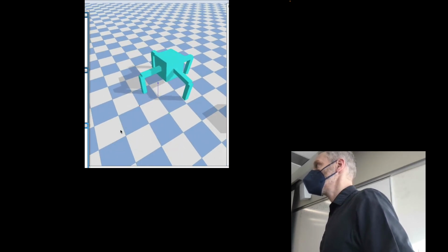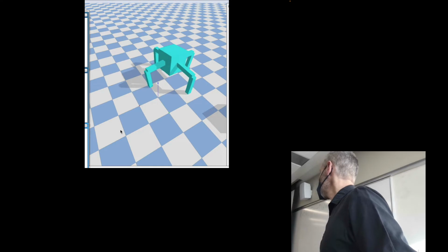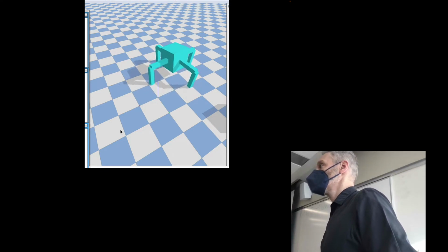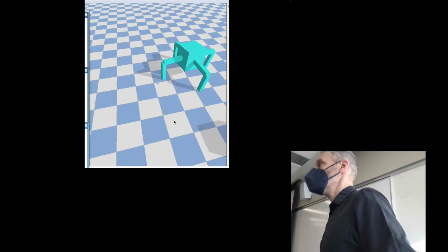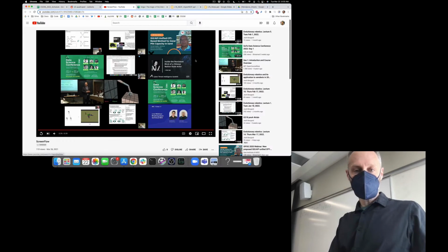We've got 8 joints, so you'll have 8 motor neurons, 8 motors. You're going to connect each of the 4 sensor neurons to each of the 8 motor neurons, which will give us 4 times 8, 32 synapses. If you want to add in hidden neurons, that's perfectly fine. Okay. So that's the quadruped.